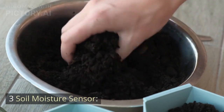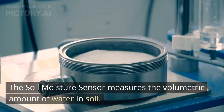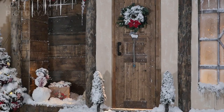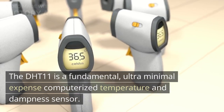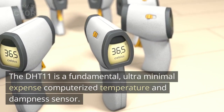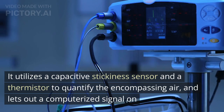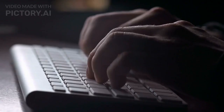3. Soil moisture sensor. The soil moisture sensor measures the volumetric amount of water in soil. 4. DHT11. The DHT11 is a fundamental, ultra-minimal expense digital temperature and humidity sensor. It utilizes a capacitive humidity sensor and a thermistor to measure the surrounding air, and puts out a digital signal on the data pin.